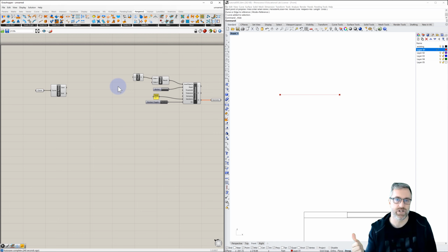The first thing that we want to do is give it constraints because we're also going to apply a force. And so between those 2 things, as we apply a force, we have to constrain the model so that it doesn't just fly away. And so we'll add forces, we'll add constraints to fix the model.